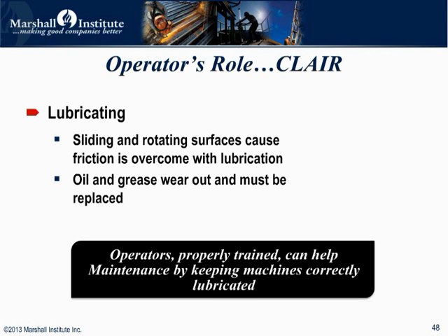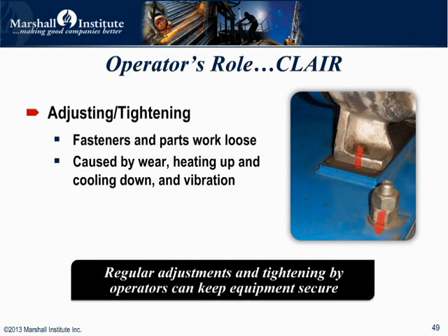Properly trained operators can perform many, if not most, of the lubrication duties on their machines, freeing maintenance to do more complex, value-added activities. Adjustment. Regular adjustment and tightening is an operator duty, and thus avoids entirely what is a chronic problem in most plants, loose and missing fasteners.